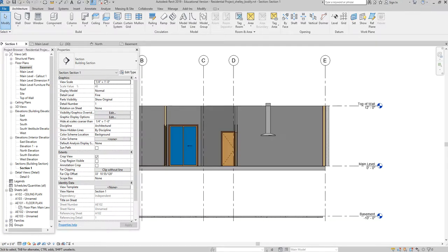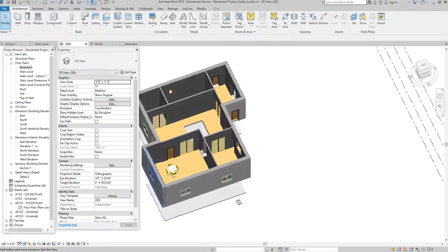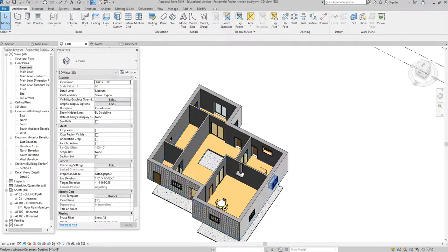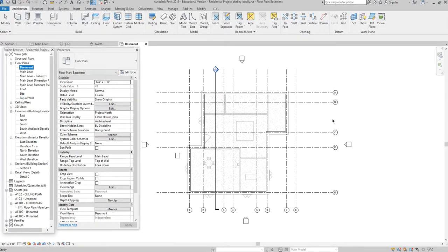Now what's nice about this is that I have the floor plate for my basement level established, right? And when we learn about stairs, my stairs will be able to go from my upper level down to my basement level. Now I'm going to turn my underlay off. None. Apply. And there's my floor. Okay. Any questions about components or floors?